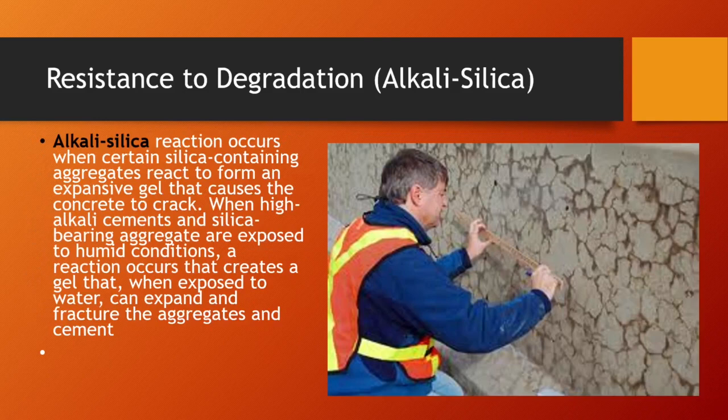Resistance in terms of alkali silica. This is a reaction that forms an expansive gel that causes concrete to crack. So think of freeze thaw, but instead of the freeze scenario, this is an expansive gel formed from silica, which is a natural product in concrete.